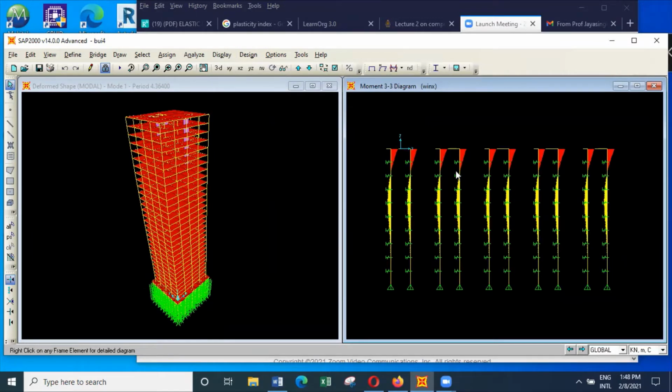So what actually happens is now I'm applying the load only in one direction. But when you look at the envelope, we apply the load in both directions, x direction and minus x direction. So because of that reason, you could not see the fact that some negative moments will act. And the pile will behave as if it's fully fixed at this particular level because the bending moment on the pile is maximum and pile is embedded in soil.